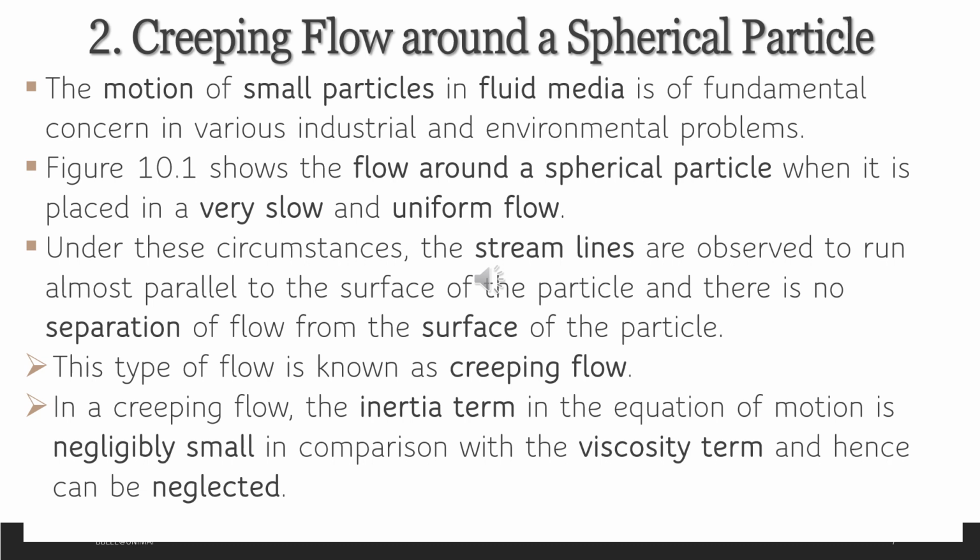We cannot solve the problem using simple manual calculation, or even with MATLAB. We need more complicated software, maybe computational fluid dynamics (CFD) software, because it involves a lot of equations to create the streamlines and the interaction between them. Now we have to assume there is no separation of flow from the surface of the particle. This type of flow is called creeping flow, very uniform, very slow flow. The inertial term in the equation of motion is negligibly small in comparison with the viscous term and hence can be neglected, because the particle is flowing in a very calm flow.